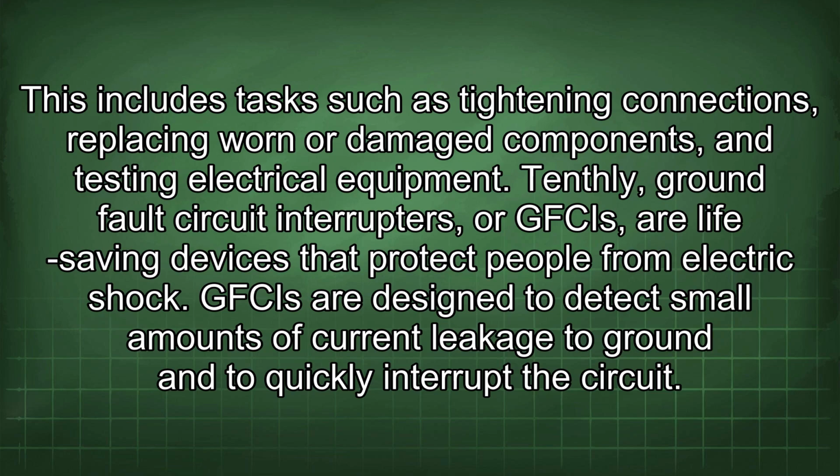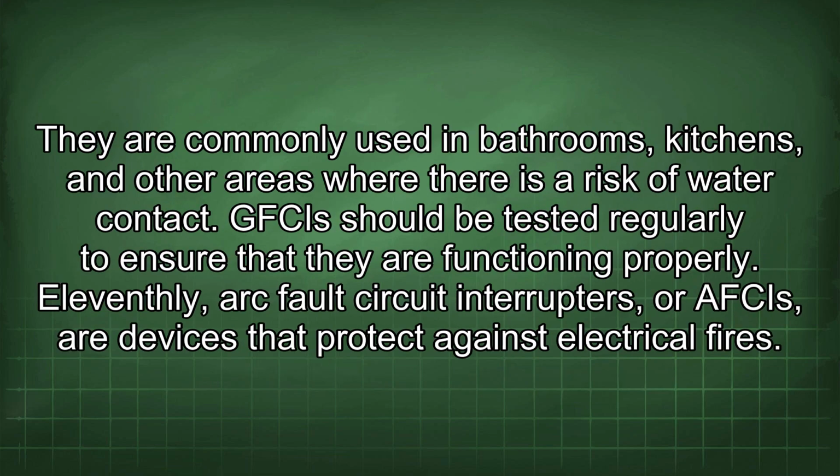Tenthly, ground fault circuit interrupters, or GFCIs, are life-saving devices that protect people from electric shock. GFCIs are designed to detect small amounts of current leakage to ground and to quickly interrupt the circuit. They are commonly used in bathrooms, kitchens, and other areas where there is a risk of water contact. GFCIs should be tested regularly to ensure that they are functioning properly.